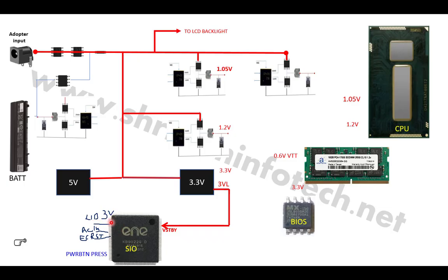Normally in this newer generation laptop, the EC BIOS is merged into the SIO. So there is no BIOS outside the SIO. On the newer generation laptop, the EC BIOS is merged into the SIO, so you won't find a BIOS outside of the SIO. The BIOS will be inside the SIO. The BIOS size may be somewhere around 128 kb or a maximum of around 256 kb. So that is the size of the BIOS.